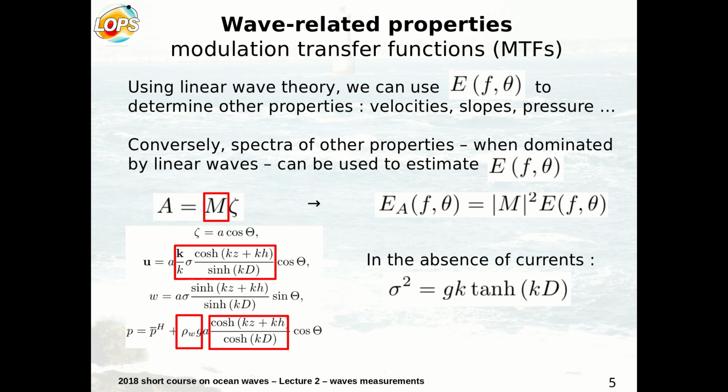And one way to go about all that is ideally, and the ideal thing here means we're going to consider that waves are linear and propagating over a flat bottom, and they're also irrotational, meaning that there's no vorticity in the fluid. If not, then that will introduce some complications, but some of that is discussed in the book. We'll leave that alone for today.